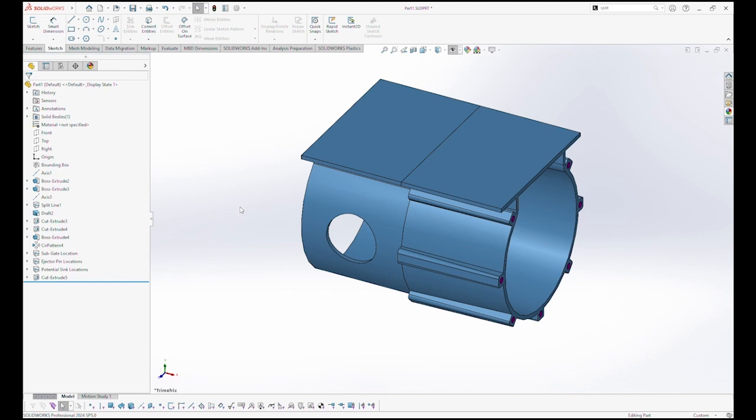There are some parts, however, that customers want a glossy finish on for either form, fit, or function. And so we can also go in and do a post machining polishing, and we can polish up to SPI standard A2 through C3 and any of the steps in between.